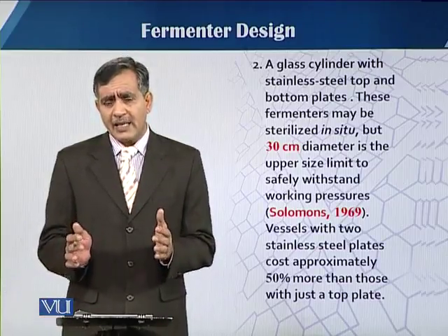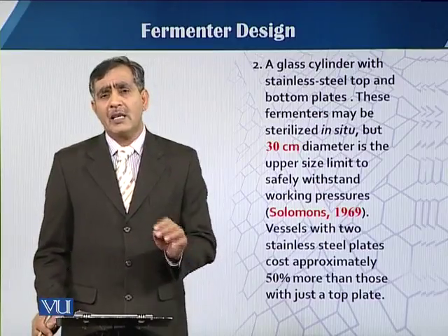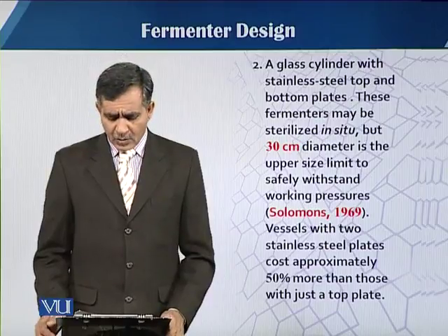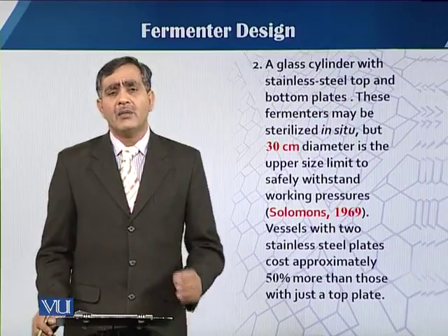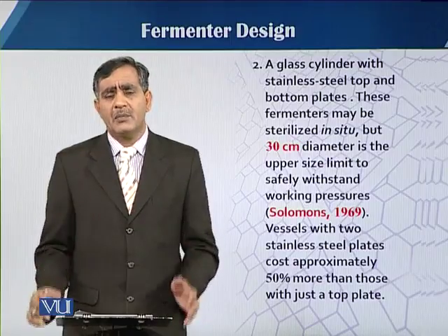In that case 30 centimeter diameter is the maximum, because that can only withstand that pressure. So that is the limitation when we use glass as a construction material of the vessels.